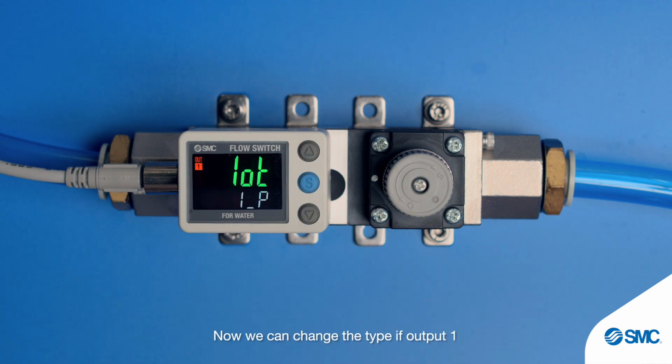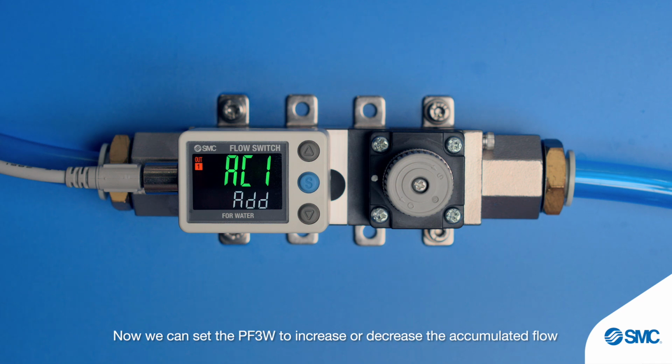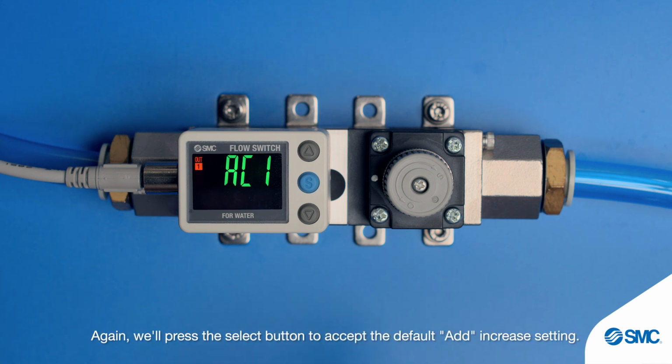Now we can change the type if output 1 is on either below or above the threshold. Here we'll leave the setting as 1_P, meaning the output is on when the accumulated flow is measured above the set point. Press the set button to accept. Now we can set the PF3W to increase or decrease the accumulated flow as fluid passes through the device by pressing the up or down buttons. Again, we'll press the set button to accept the default add increase setting.